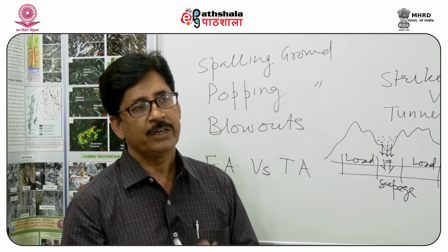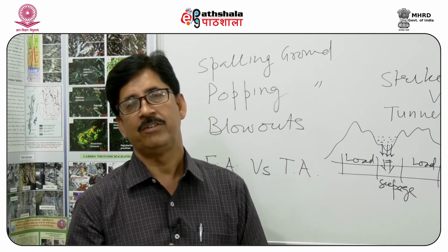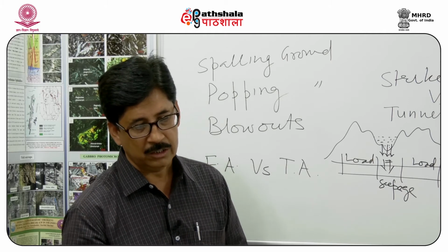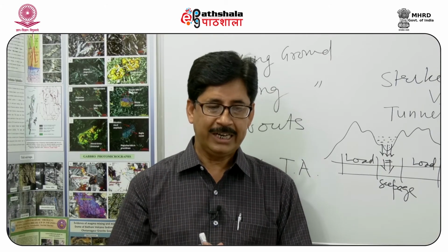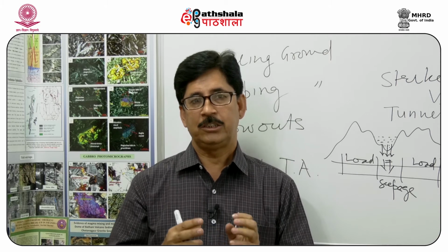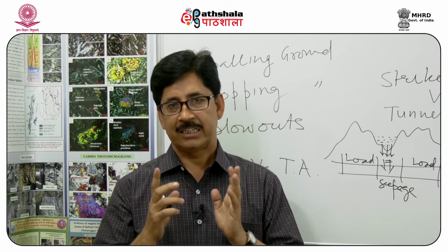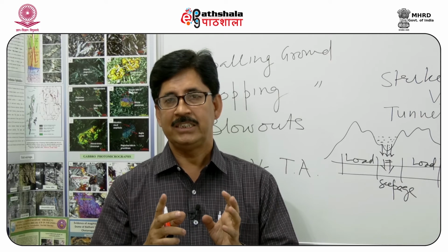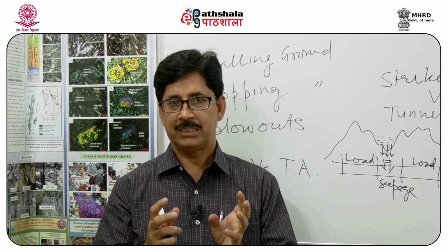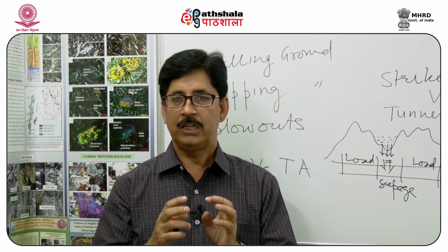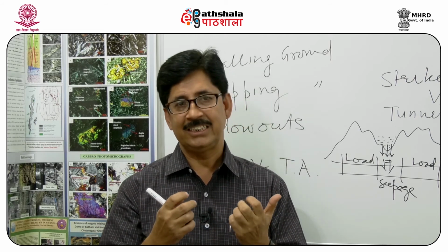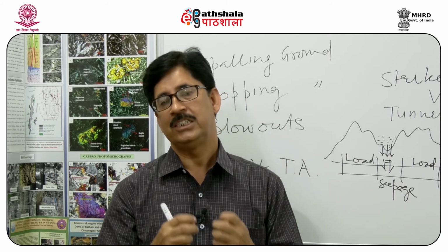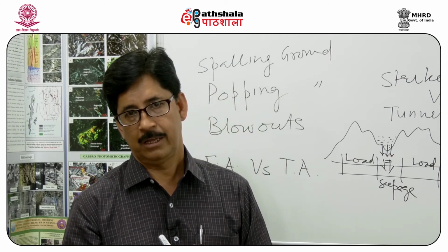Now we have two different concepts which are prevailing as far as construction of tunnel is concerned. One is New Austrian tunneling method, which is also known as NATM method. In NATM method, it is being said that when you excavate the rock, and if there is a destabilization of rock mass because of excavation, we will allow that destabilization and we will allow the rock mass to readjust itself to the present stress distribution condition.